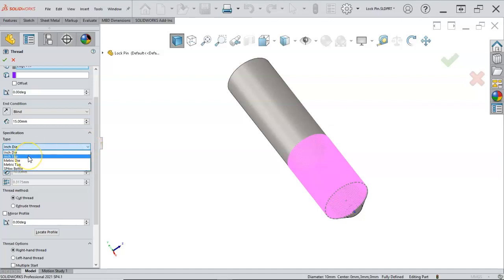So we're going to go with external, which would be a die. The die is the tool that as we turn it around the part is cutting the threads, or most commonly cutting the threads. And then we can also single point on a lathe or in a CNC, which is a tool traveling across that face in a repeating fashion till it generates the geometry.